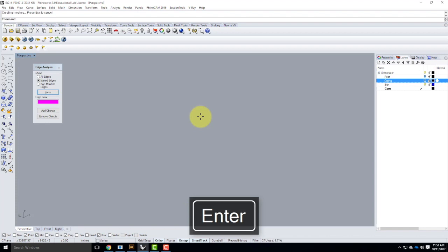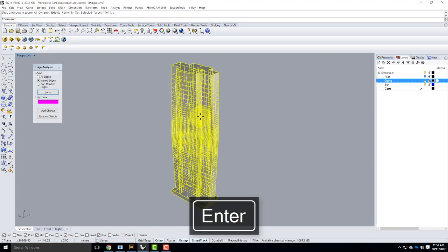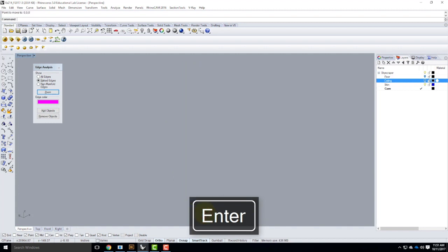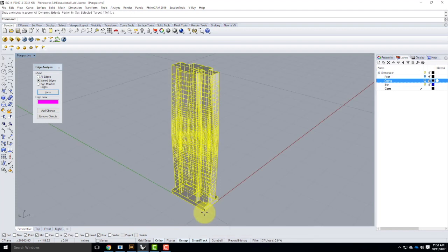Remember, this is the same thing that happened when we did the laser cut. We just switched from a huge object to something small. So immediately Z, enter for zoom, followed by S for selected, enter. There it is again. It's also not a bad idea at this point to move the object back to 0,0. It may have moved. So I'm going to do move. We'll go back from this point, 0,0,0, and then Z, enter, S for selected, enter. There we are, right back at the origin.